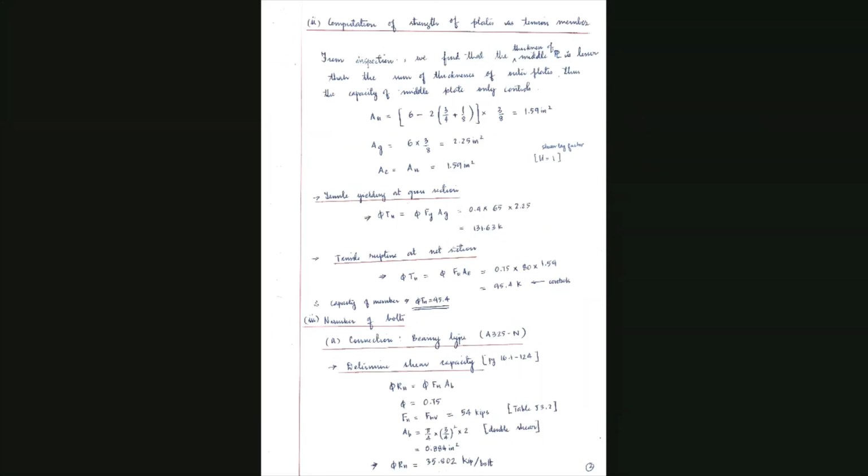Now here again, if you take a look, I've taken the value t as 0.25, because of this length. You can choose based on these. It's the same. So I have taken a value of 3 inch. The maximum spacing is 3 inch. So I have made the layout. I have calculated the value of edge distance. I have calculated the value of spacing.